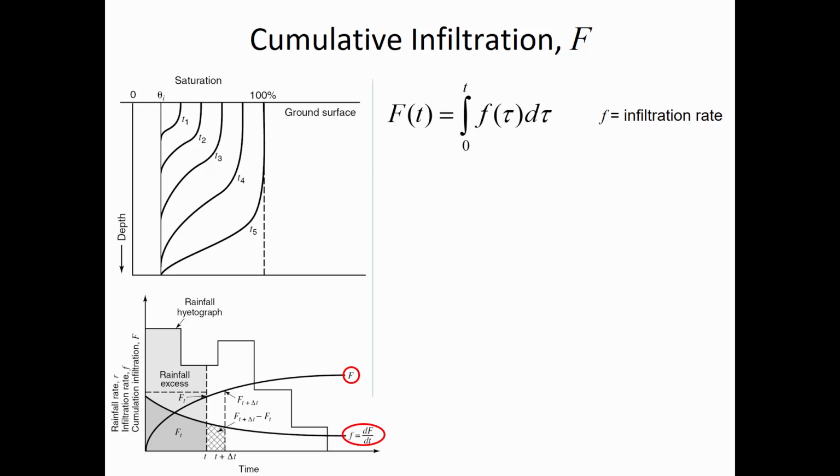So that means that there's going to be ponding at the surface. There's more water at the surface than can be absorbed by the soil. And the Green-Ampt simplification requires that. It won't be accurate. It'll be even less accurate than usual if we don't have ponding at the surface. So that's one of the things that I have to tell you, is that the hyetograph of rainfall needs to be above the infiltration curve for us to have any hope of accuracy.